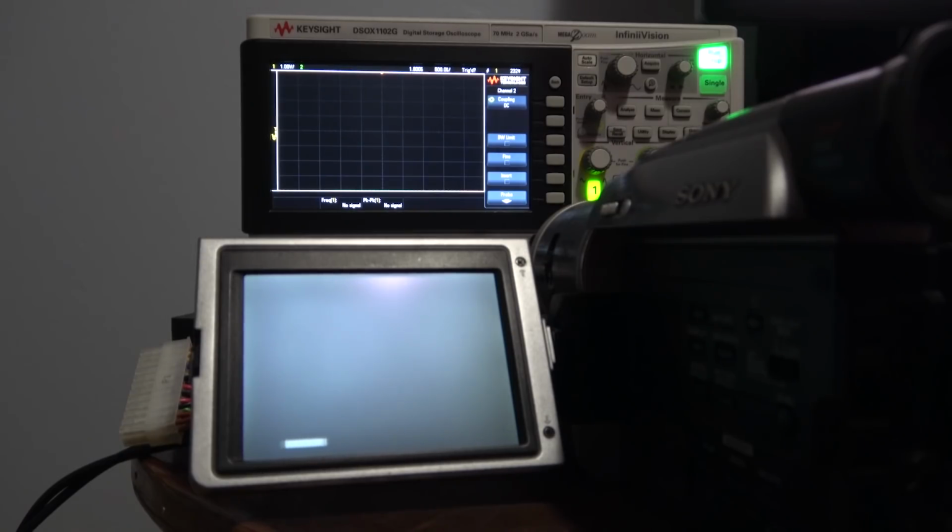And I'd also like a trigger, which is why I wanted to have that extra resistor. So what I can do is, if I have a 10K potentiometer and a 20K resistor, I can make it so the potentiometer only affects the first third of the range, and then we can have a button which will pull it to high. So if we see that happen, instead of updating this position, we can fire a missile or something.